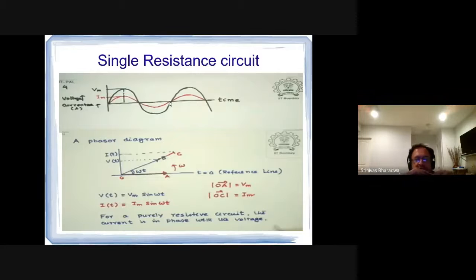Typically, it will have some internal resistance, just like your capacitor also will have some internal resistance. But phi equals Li, so therefore V equals L di by dt. If di by dt is 0, the V across the inductor will be 0, but it will behave like a short. A capacitor, on the other hand, will behave like an open circuit.